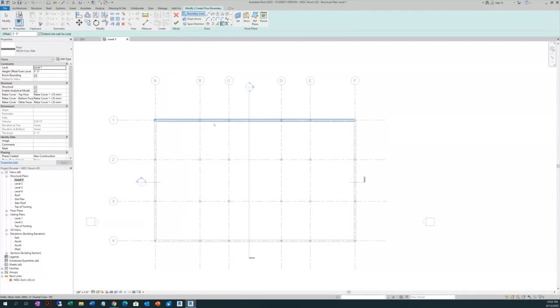Then here, what we need to do is see here on the draw tools, you have many options, but the option that you are going to use is pick walls or pick lines. Let's go pick walls, okay? Pick walls. Carefully, because if we don't pay attention, it is going to keep picking, and then it's going to be a magenta over a magenta. Then we need to go back and delete it. Pick walls.